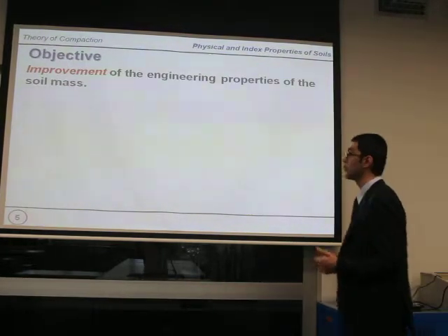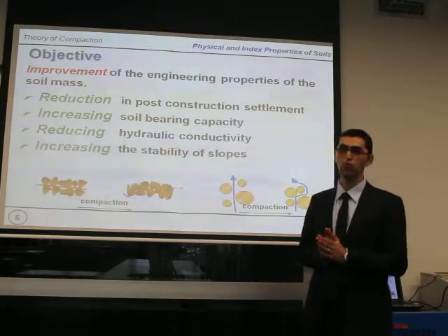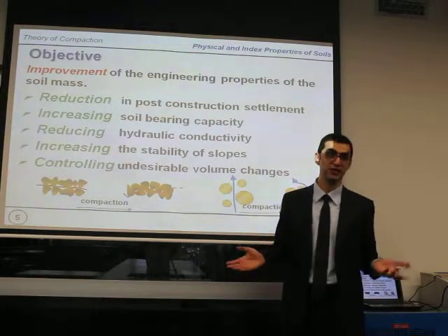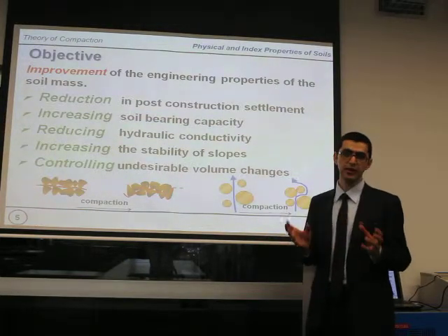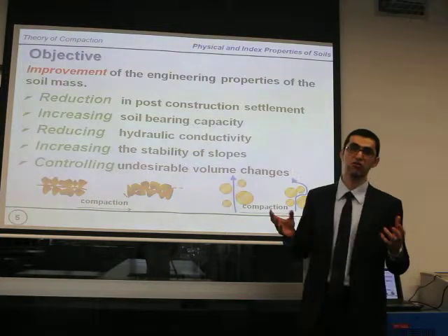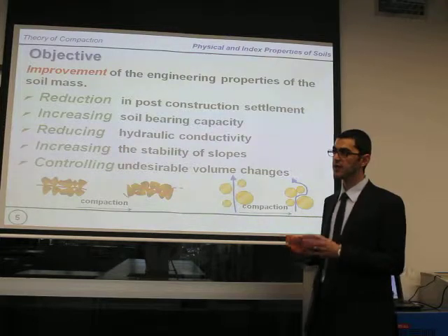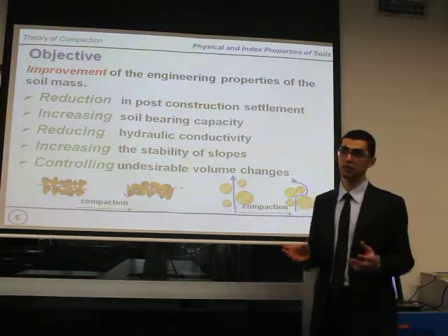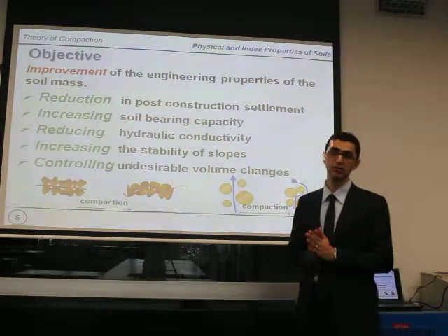But why do we need soil compaction? As we all know, soil is used in many projects as a construction material. However, in some cases, the natural state of soil is not sufficient to be used as structural fill. Therefore, we need to somehow improve it. One of the effective and conventional methods for improvement is compaction. So the main objective is improving the engineering properties of a soil.